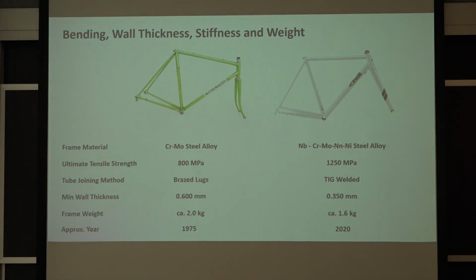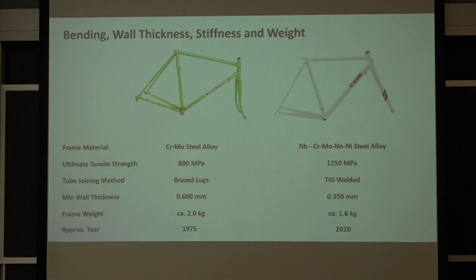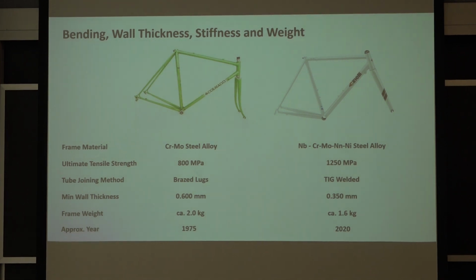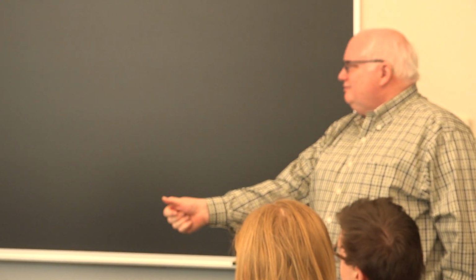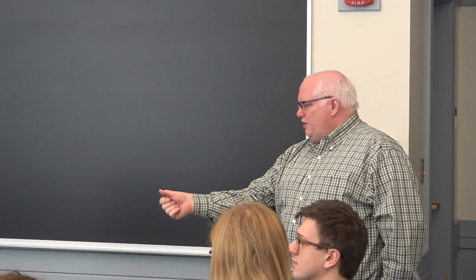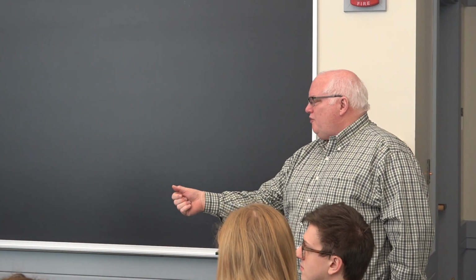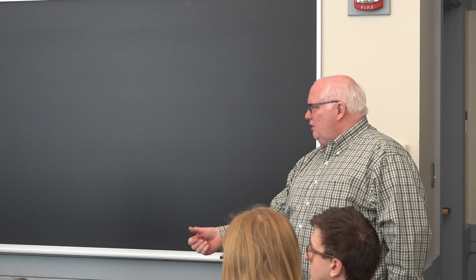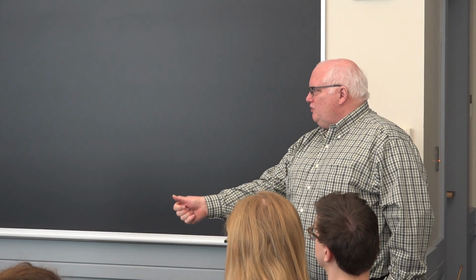Question over here? Yep. I was going to say, a few years ago, I was at Chrysler, and it turns out the handle on the car, you know, the lift up like this and you push it with your thumb up here, they had to increase the thickness of the sidewall because of the thumb. This is the door or the lift gate? This is the door. The door, okay. This is the driver's door. But they had to go from half a millimeter to 0.6 millimeter because the thumb was going to dent the